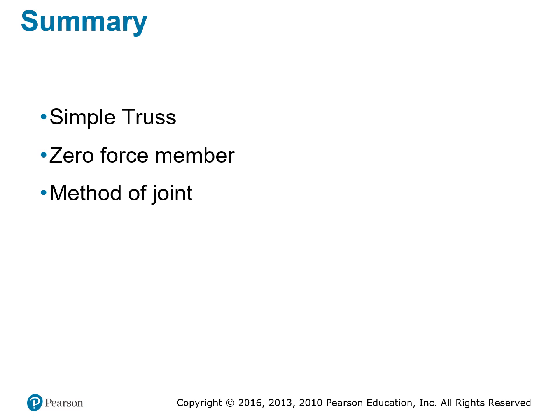Okay, so I want to summarize this. This is a very important topic. We're going to do some more examples in the lecture. So first you have to know what is a simple truss. A simple truss is normally just a triangle shape. You can expand it by extending the triangle to the other direction. Zero force member, we have two cases.